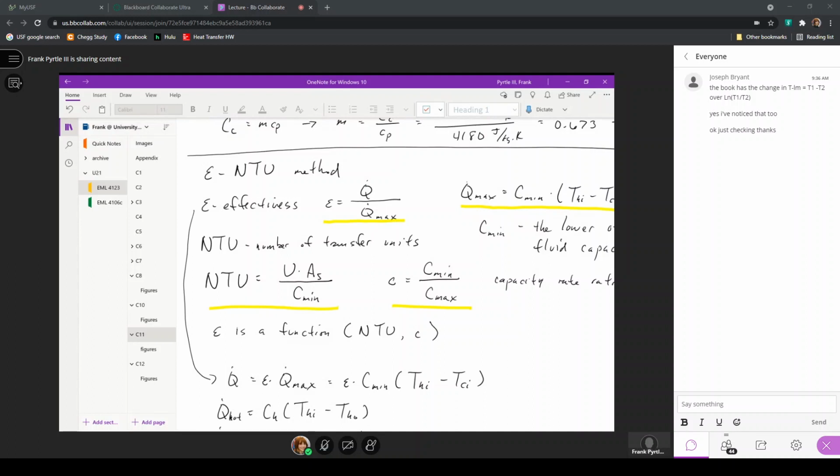So if I pull the heat exchanger off the shelf and I supply a hot fluid and a cold fluid, and I measure the mass flow rates of those two fluids and the inlet and outlet temperatures, then I get the capacity rates and the temperature differences that would occur. And if I've selected that heat exchanger with a note where the surface area that is shared for heat exchange is known, then I can actually calculate what the overall heat transfer coefficient is.